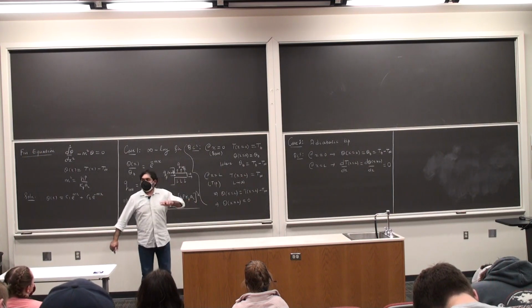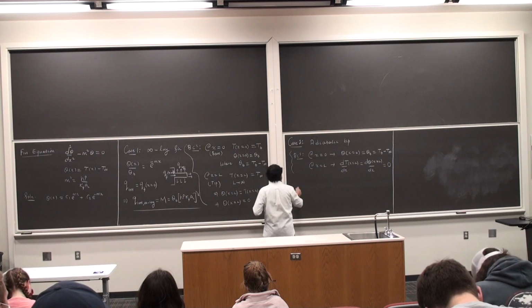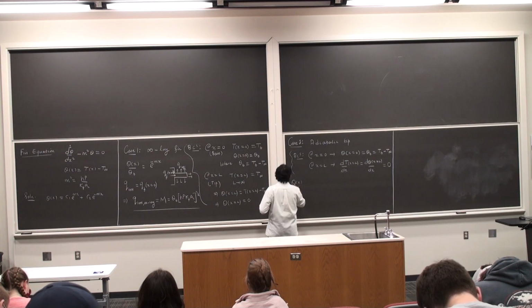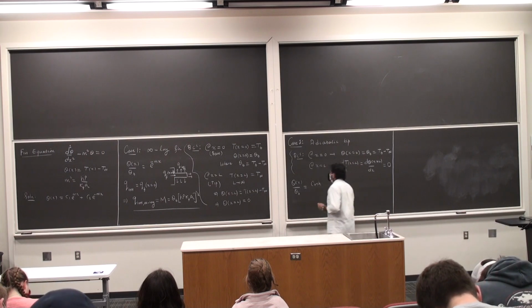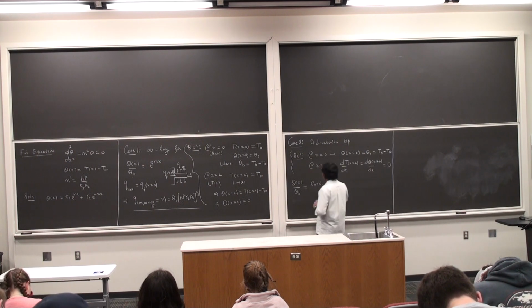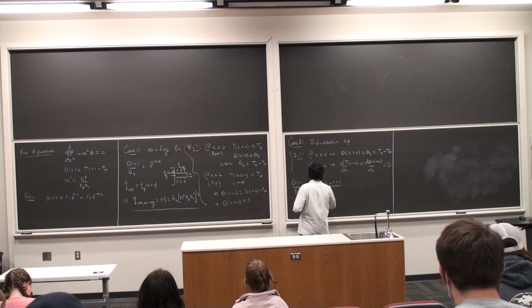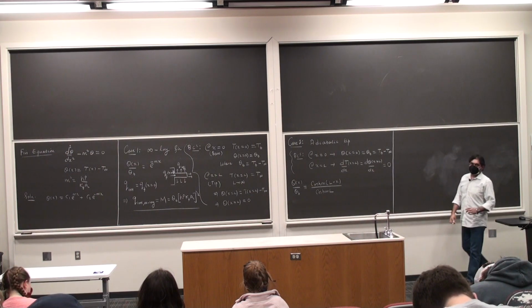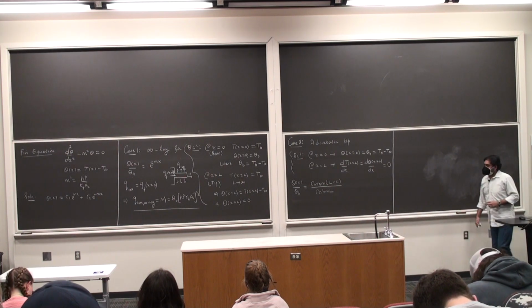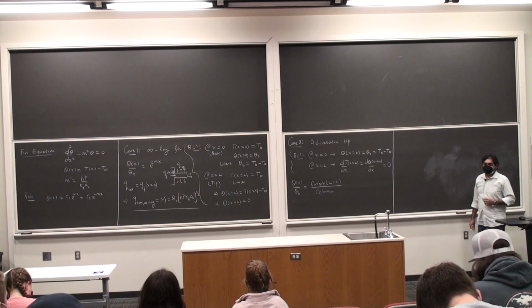Substituting these two, we obtain the solution. Cosine hyperbolic, okay, m times (L minus x) by cosine hyperbolic m times L, where little m has the same meaning as you've seen there in the first panel.